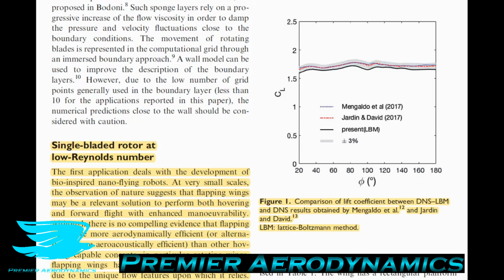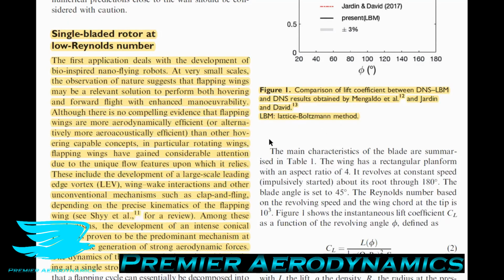The other reason why potentially they needed a finer grid is the time step. So the grid heavily determines what the time step will be for the Lattice Boltzmann method. So to get the right time step, they needed to reduce the grid resolution. That's another potential reason. I'm not sure what the reasons were. They didn't get into it in here. I'm not sure if they found them, but those are 2 potential reasons based on the Lattice Boltzmann method.